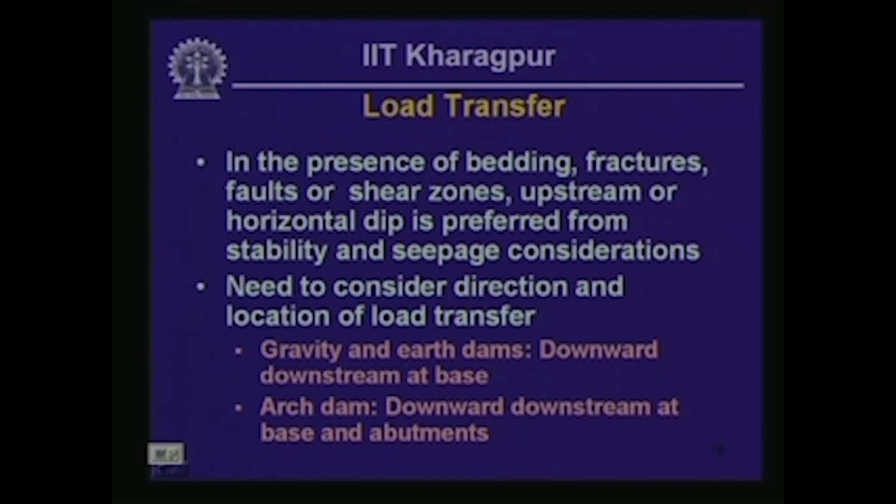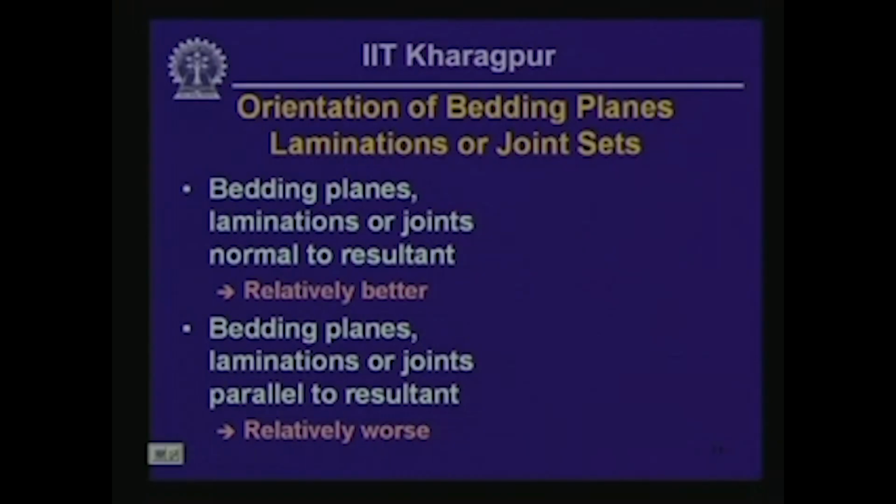Then we also need to consider the direction and the location of load transfer. We are going to look at the relative direction of the resultant that is imposed on the foundation soils, and what is the orientation of these resultants with respect to the planes of weaknesses that we might have within the foundation rock. So let us consider those things in the following.